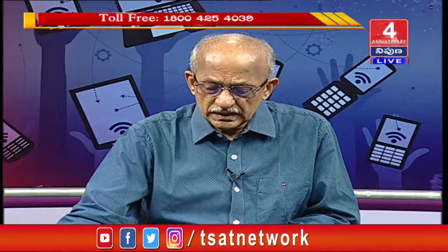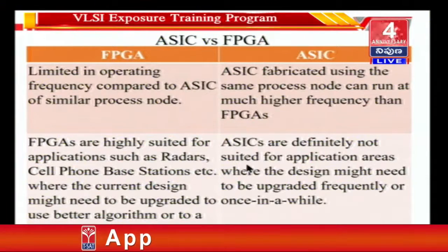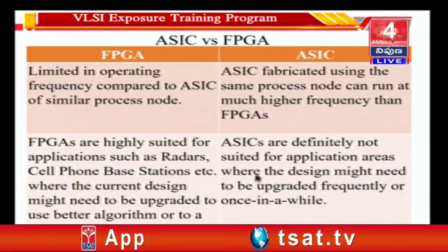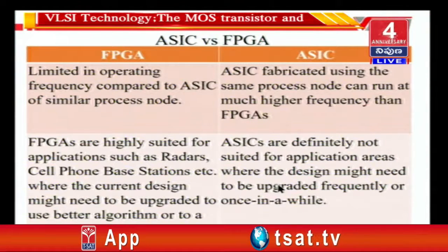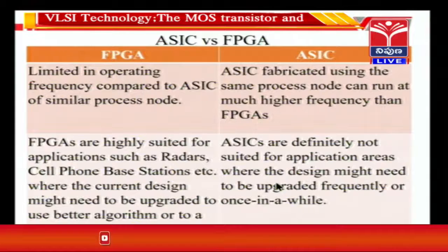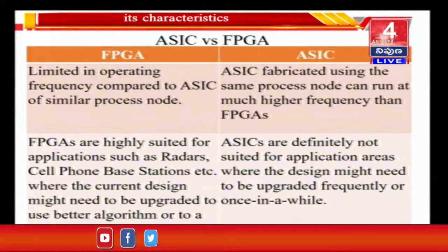ASICs are definitely not suited for application areas where the design might need to be upgraded frequently, or even once in a while, because you cannot change the functionality of an ASIC. You cannot upgrade an ASIC to a better algorithm simply by changing a few lines of code in the design. You'll have to go through the whole process of manufacturing once again, which is very, very expensive.